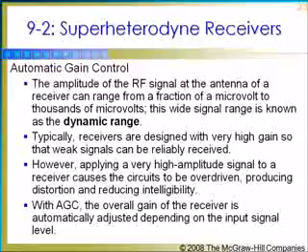This reduction in gain eliminates the distortion normally produced by a high voltage input signal. When the incoming signal is weak, the detector output is low. The output of the AGC is then a smaller DC voltage. This causes the gain of the IF amplifiers to remain high, providing maximum amplification.